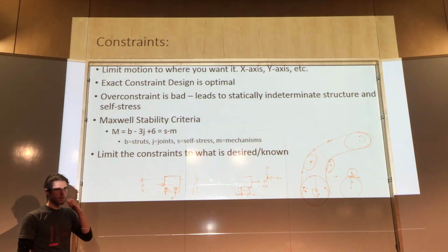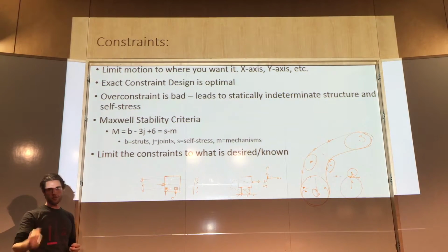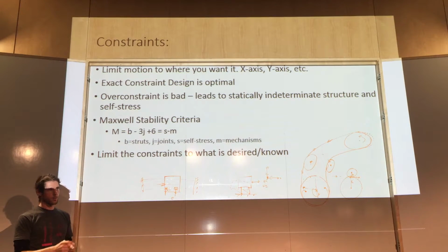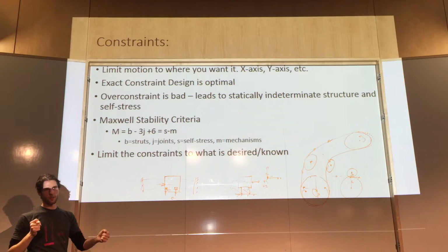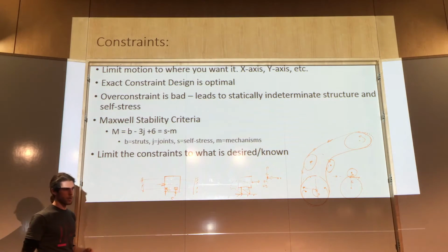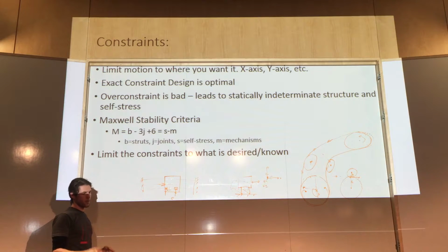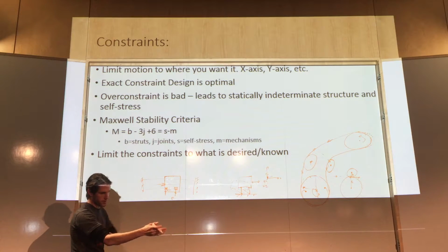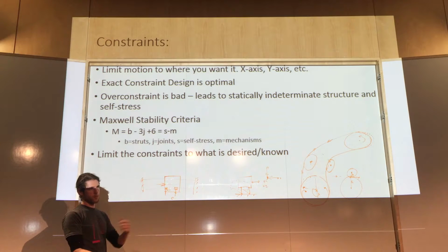And I'll do that if I'm trying to build a rotary joint for a robot or something like that. I will start to calculate out the spacing between my bearings so that I can actually get the stiffness that is required. So I might say, I need to reach this far out with this length of a beam. I'm going to have this much torque on it.